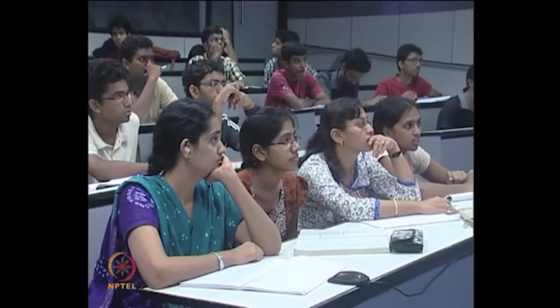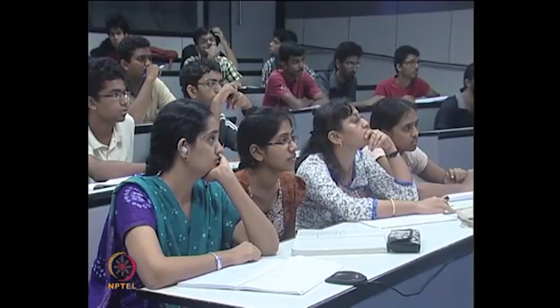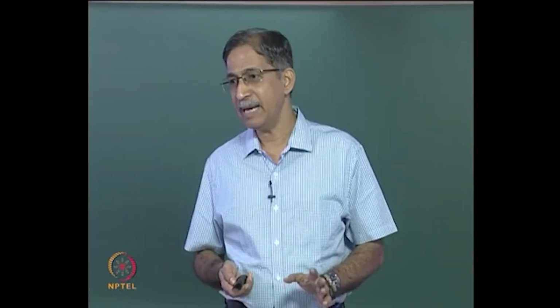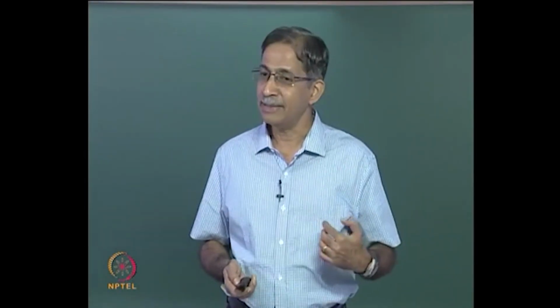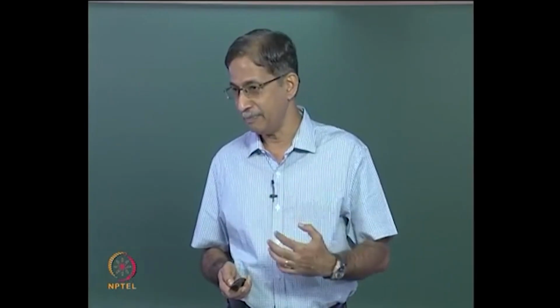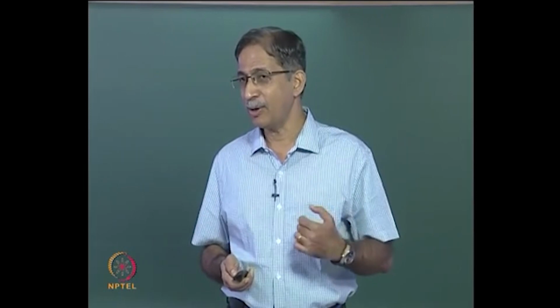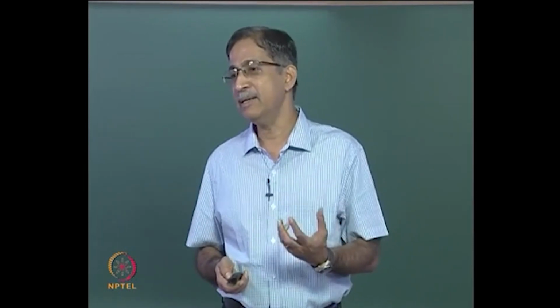Yes? X, Y and Z are global. Okay, I have marked it there. X star, Y star, Z star are local as per our standard convention. X and X star need not be in the same direction like in a continuous beam. In this orthogonal grid problem, it will be either 0 degrees or 90 degrees.